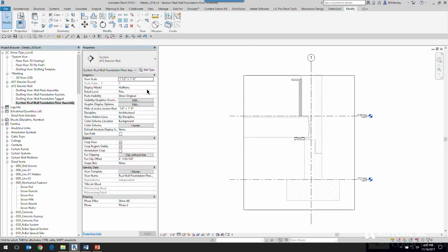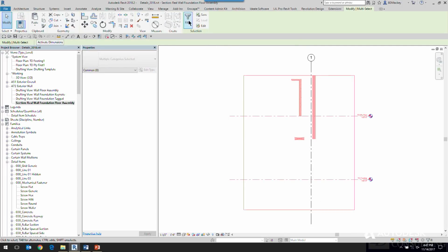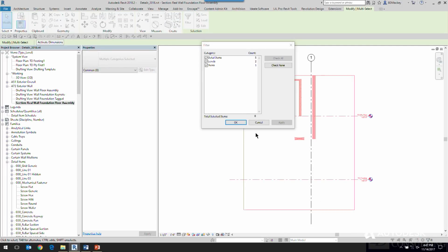If it's over the top of the model, I'm not a big group fan because groups slow Revit down and groups are very buggy. If you wanted to just group it all to copy it to another project, I don't get it. Because even if this was over the top of the model, if I need to copy all the detail components, I just say don't display the model. I do a selection window. I make sure I only have detail items. I copy it to the clipboard. I go back to the other file and I paste it. So you can still copy, paste, etc. That's my theory.